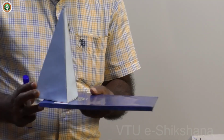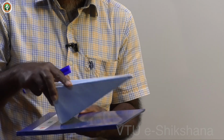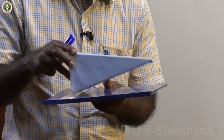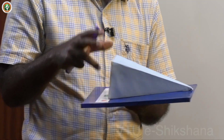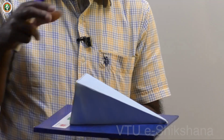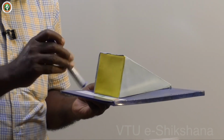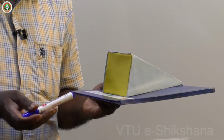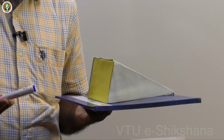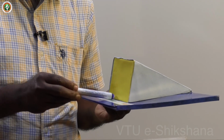So, for information, if this is the edge condition, then only you can rotate and keep the slant face, this triangular face, on HP. For all pyramids, slant faces are triangular faces. First position, second position. Then they may give a reference, the base edge on HP inclined at 45 degrees to VP or 30 degrees to VP, or the axis inclined at 30 degrees to VP or 45, as usual for the other problems.